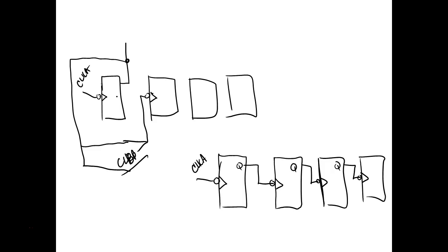But what we're going to look at now is that's why they separated. That's why we have two clock inputs. So what we have to do when we set this thing up is connect the QA output back to the clock B input. On the 7490, the 7492, and the 7493, we have to do that.